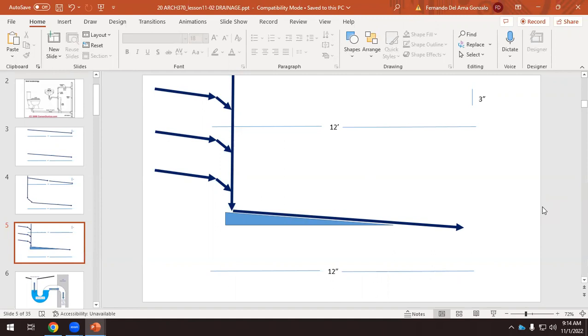So we have something solid here, and then that will hold. But when we have, especially in a parking lot, we don't get to the underground. We just have the main horizontal branch hanging from the ceiling. So this is a very important part, and we have to reinforce that, and we need a lot of hangers. Here you see that we have something that is connected to the ceiling, this element there, you see? When we have a connection with a vertical pipe, this connection has to be very strong